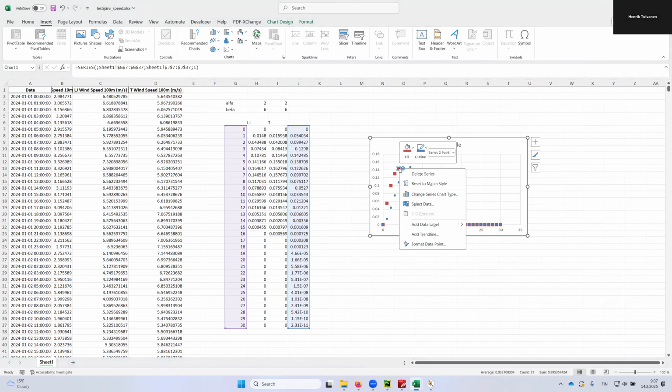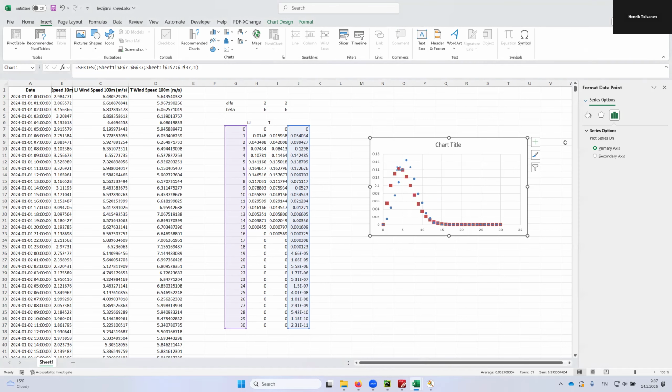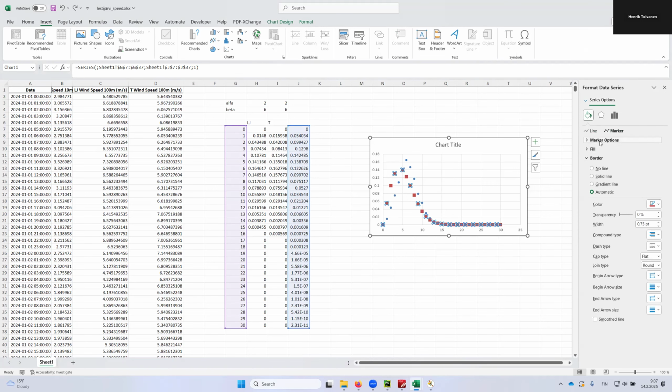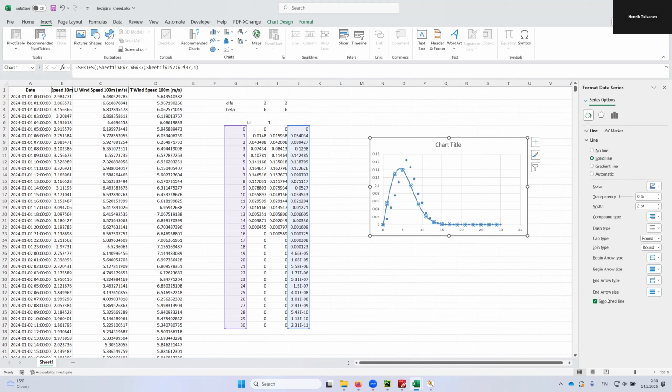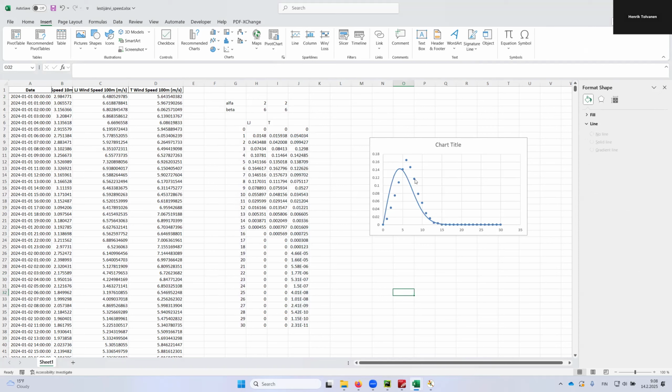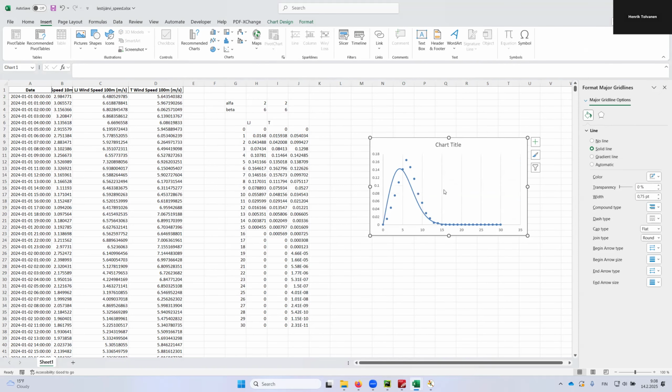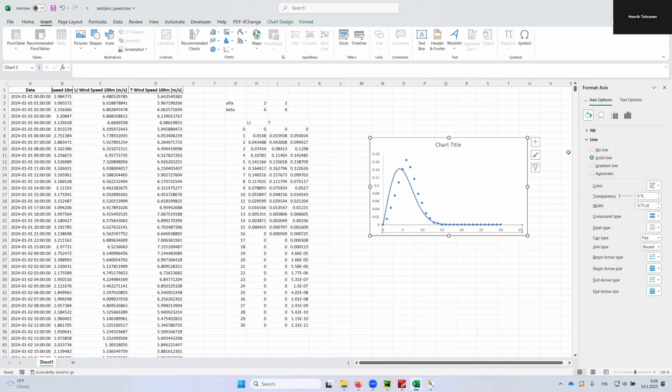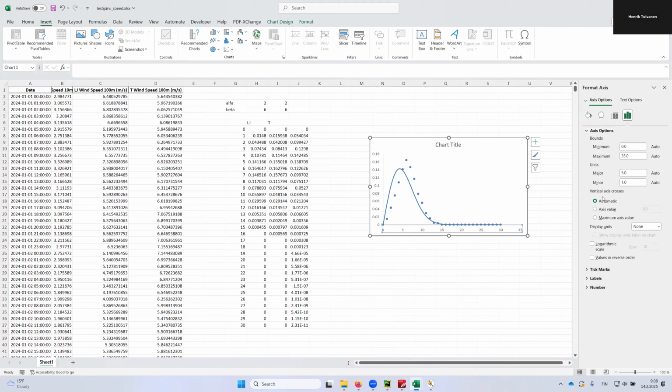And this Weibull distribution, actually, I can make it in a way that it doesn't have these markers, it rather has a line. Oh, no, 1 point selected from there. So now, no markers, just a solid smoothed line. So we'd have to get these points to match the original data that we have.